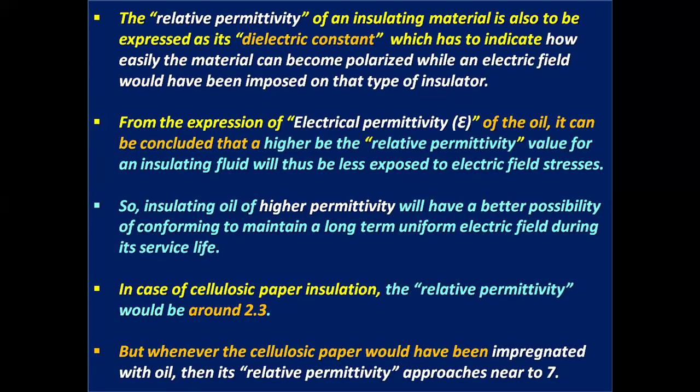The relative permittivity of an insulating material is also expressed as its dielectric constant, which indicates how easily the material can become polarized while an electric field is imposed on that type of insulation.